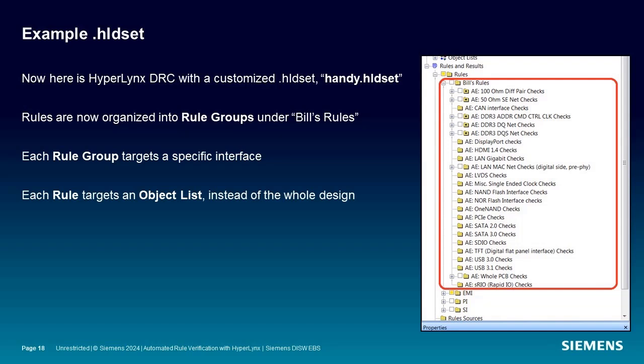You can copy and paste common rules that have parameters that will change for or vary depending upon the nets. For instance, you will want differential impedance checks, but the targeted differential impedance will change from DDR2 to DDR3 to DDR4 and 5. Same goes for other protocols. Just follow the design rule guidelines for whatever structures are on your board and use the out-of-the-box rules to target them. Some rules will run on the entire design, and some will only run on a certain area. The rule groups can focus the rule scope or use object lists to target specific groups.